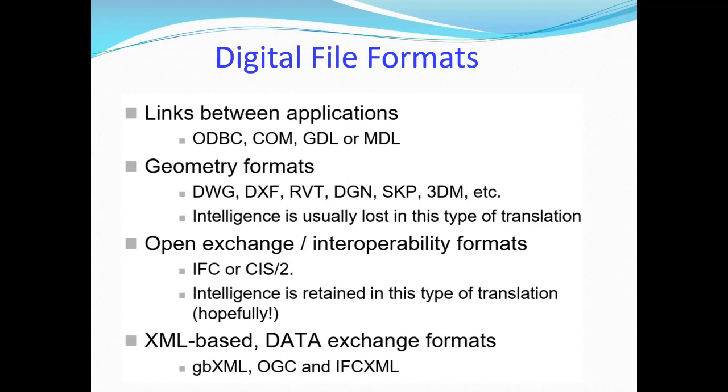So all Revit and all BIM software are supposed to enable this IFC format. Once you finish the modeling, you should be able to export or save as an IFC file. Then you can open it in any other BIM software, or any other IFC-enabled software like ETABS, SAP2000, Tekla Structural Designer or SAP Pro.